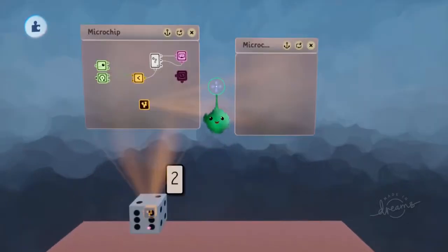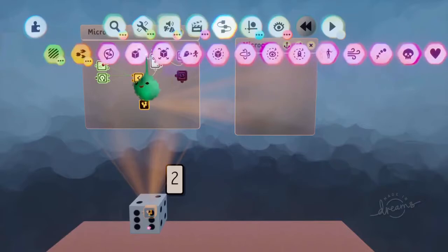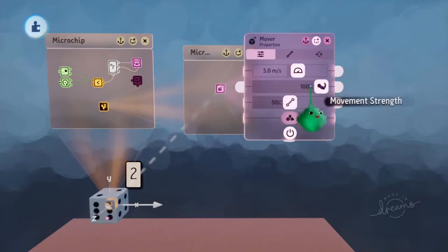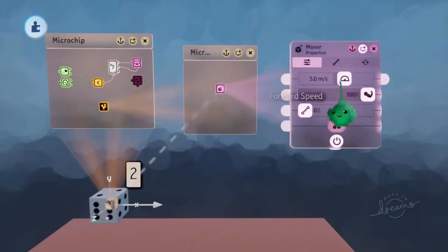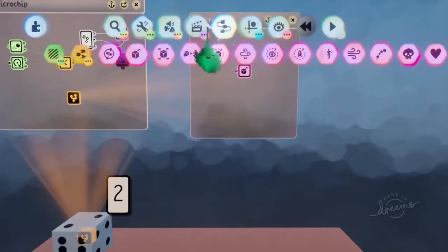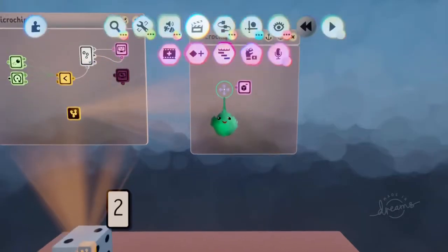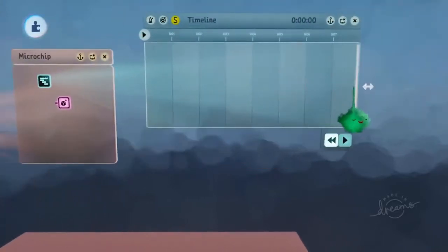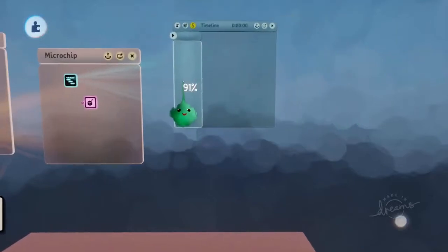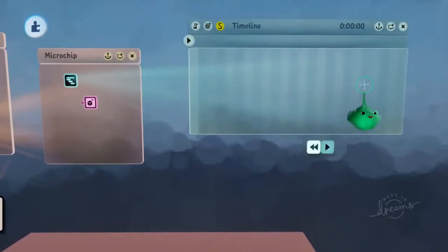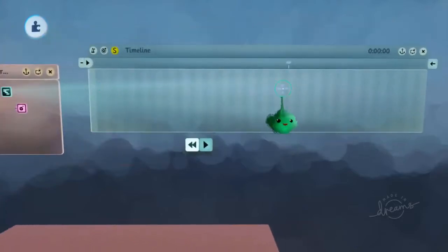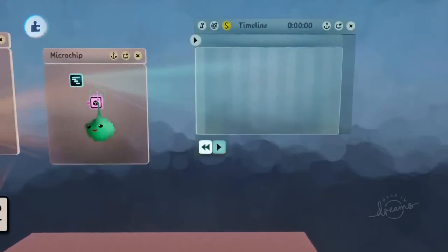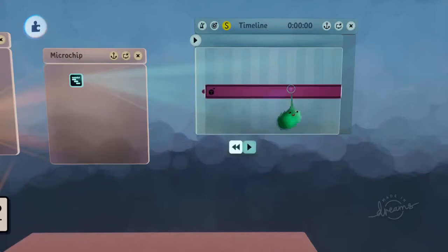And in here we want to have a mover on that. It will have full strength and low damping, and probably quite low speed as well. And it would only be triggered briefly. So I'm going to have a timeline, and we'll zoom into it. If we drag the end with X, make it short, and then L1 and right to zoom into it. So this shows like 1 second over a large area. So you can do very fine timing to it. So let's put the mover on here.